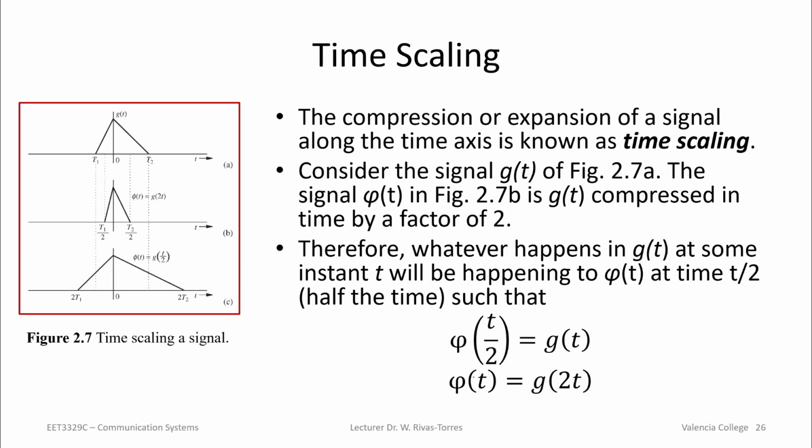Time scaling. Time scaling is one of those interesting things that we can do to signals. I always find it sort of a fun thing. So let's say that my original signal looks something like this. Let's say that I want to compress my signal by a factor of 2. Well, in order to compress the signal, and let's call the signal phi of t, what I do is I take all the t's and multiply them by whatever compression number I want, which in my case is 2, right?